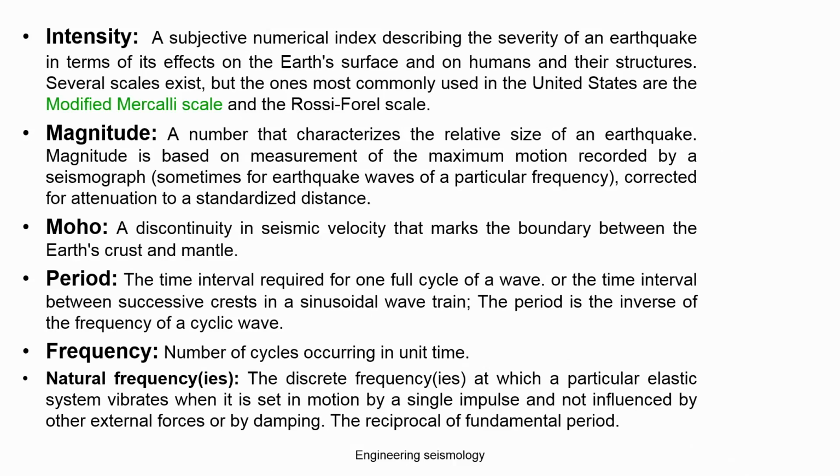Intensity is a subjective numerical index describing the severity of the earthquake in terms of its effect on the earth's surface, on humans and their structures. Several scales exist, but the most commonly used are the United States Modified Mercalli intensity scale and the Rossi-Forel scale. We will be discussing intensity in detail in one of the classes.